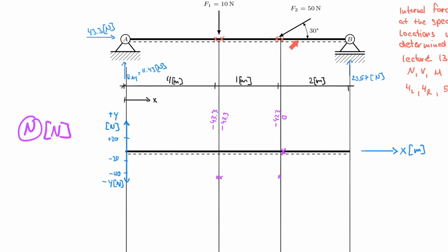And here everything has to remain zero because there's a roller here and the roller is pretty much pulled to the left, and because it doesn't resist the pull, it is free to move, it has a degree of freedom in that direction, there can be no force activated in here. So think about what force is. Force is really a resistance to deformation. And so this here really resists the deformation, whereas this one doesn't. It can actually move with it. So it's zero. And therefore, I can now extrapolate my understanding and really draw the values everywhere along the x-axis.